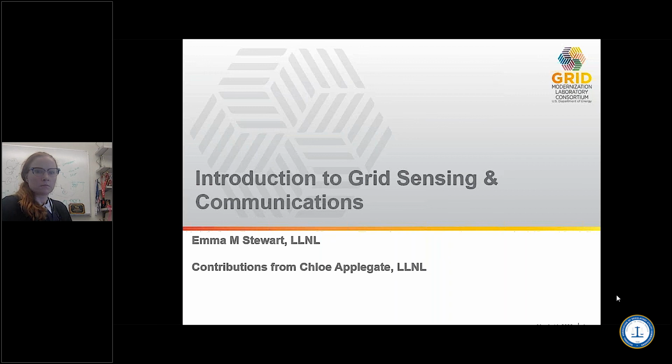It allows you to change voltage in a much smaller form factor, but it doesn't provide electrical isolation. This is actually what voltage regulators are out on the distribution circuit. They're variable tap auto transformers. So the trade-off is that they are a different type of transformer. They provide no electrical isolation, but they can be smaller. They can provide a smaller range of voltage change, and they're more cost-effective for some applications.